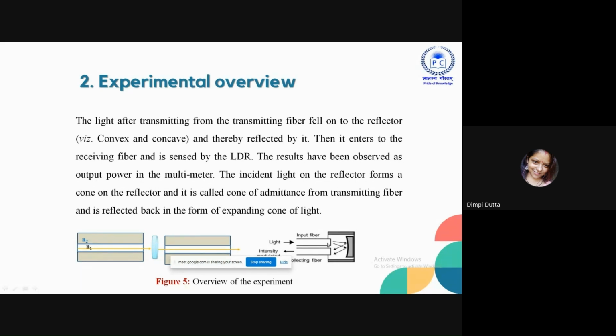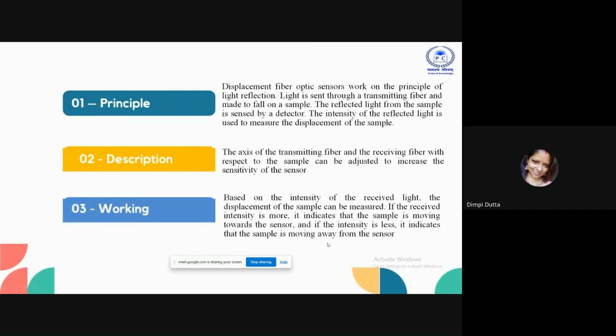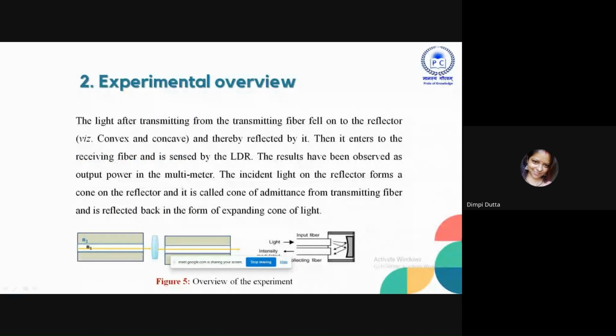During the experiment, as I've already mentioned, two basic optical fibers have been used, and in that, I would like to point out one important point, the evanescent field. You can see there is a chamber in which I have changed the medium, because as I mentioned earlier, the evanescent wave also has an impact on changing the information surrounding the optical fiber.